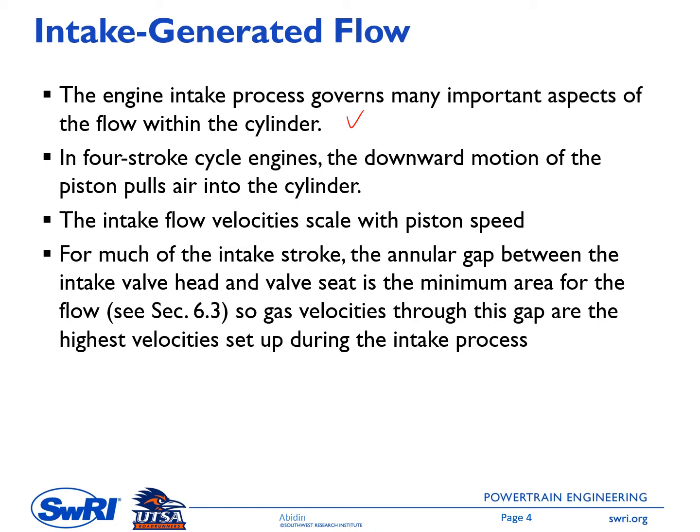So as the engine is operated at high engine speed and thus higher piston speed, the intake flow velocity increases. For much of the intake stroke, the annular gap between the intake valve head and valve seat is the minimum area for the flow. We have talked about this in chapter 6.